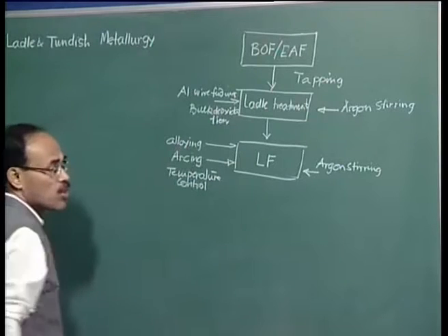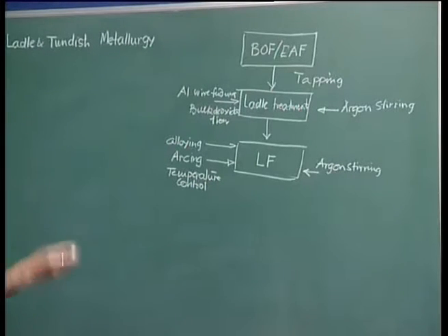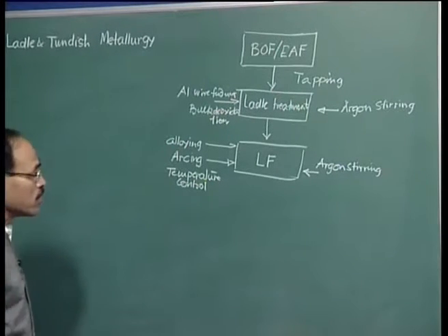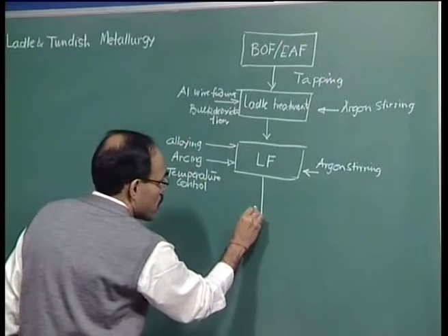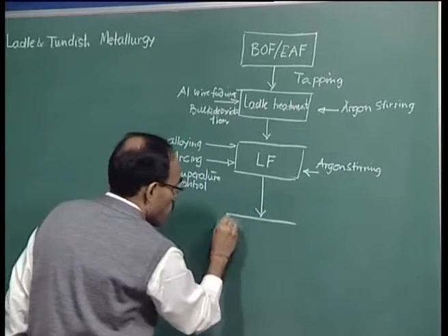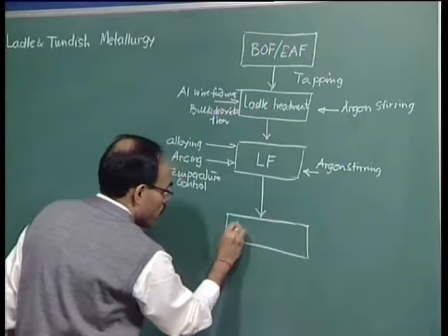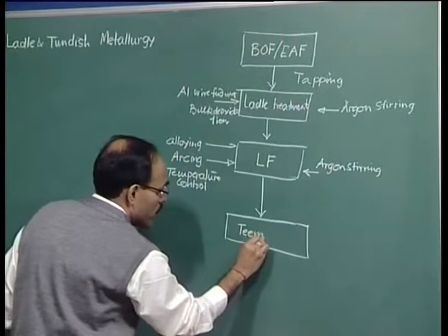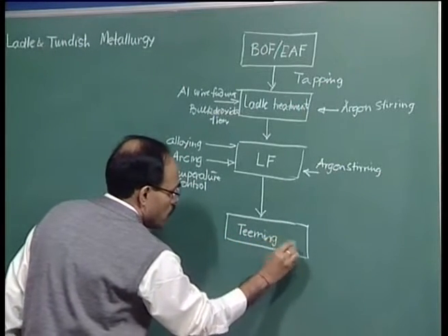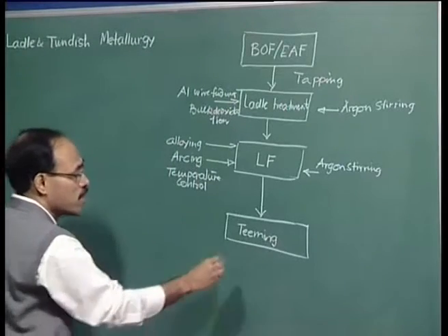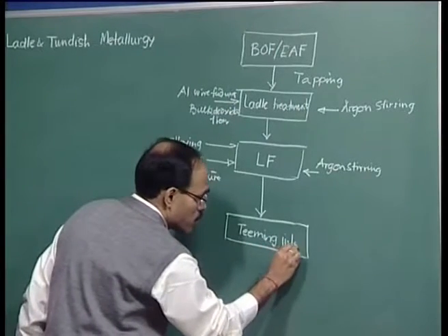Basically, we adjust composition and control or enhance the melt temperature, and following this we have teeming, and this teeming is into the tundish.